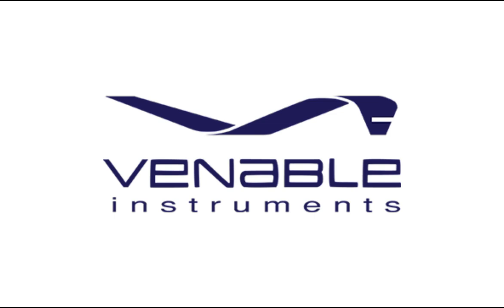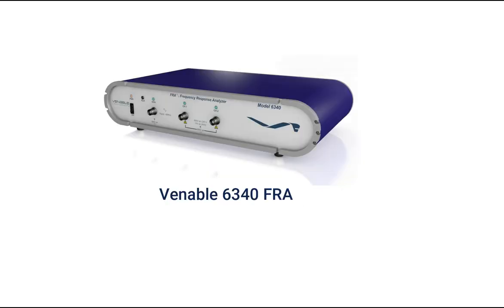In this video, I will show you how to use the Venable RLC measurement accessory along with the Venable FRA to measure and characterize the impedance accurately and easily. In this tutorial, we will use the Venable FRA 6340 and Venable RLC Measurement Package to measure the impedance of the 2.2 microfarad electrolytic capacitor.